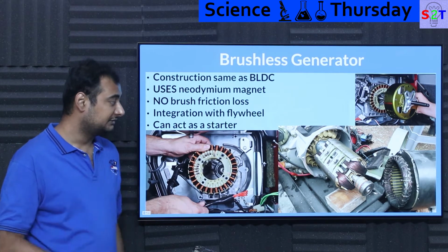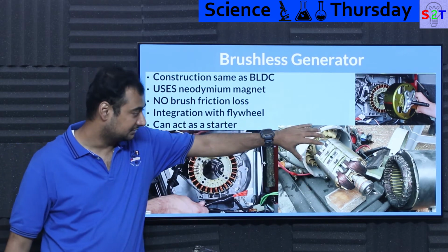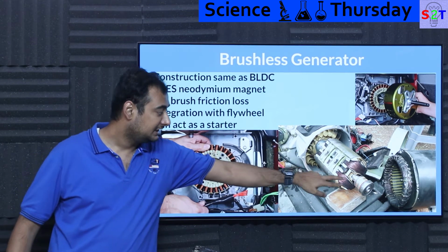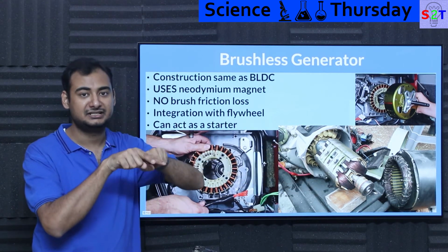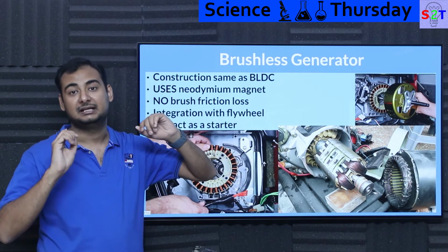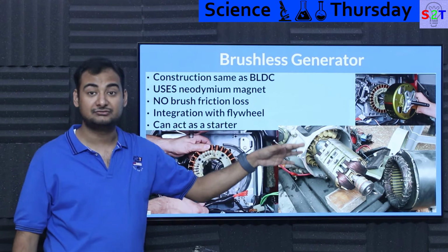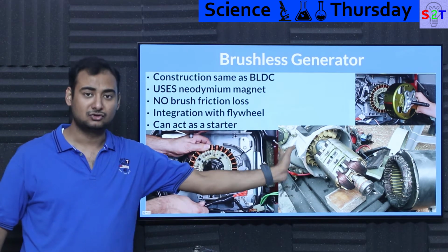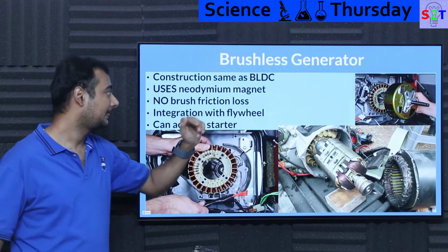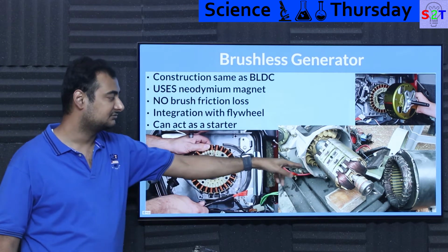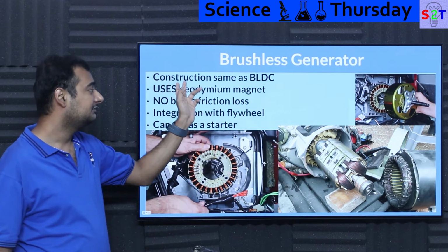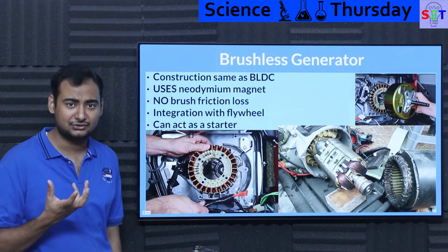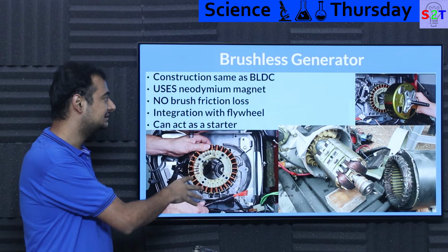So the core of that inverter AC, this is the old system where you had an electromagnet in the center, which was the rotating electromagnet, and you had slip rings. Slip rings send DC electricity into the core, and you control the intensity of it to control the voltage, and the RPM will control the frequency. Now all this is gone. Take this, throw it away. Then you will have what we call the rotating field type. So what you now have is basically a BLDC motor. If you have ever seen a large BLDC motor used for drones, it's exactly like that. Control C, control V that.